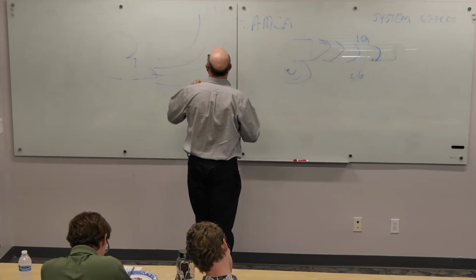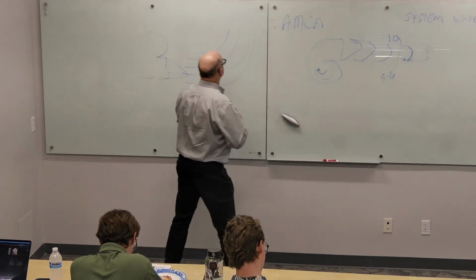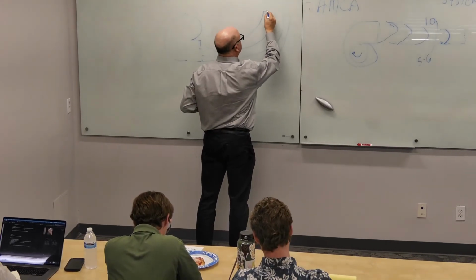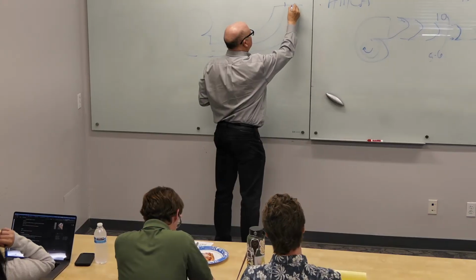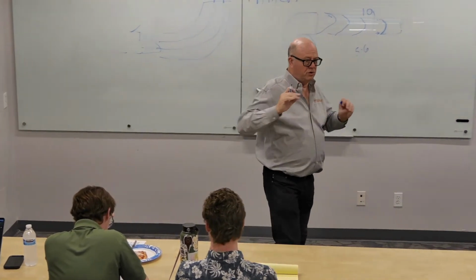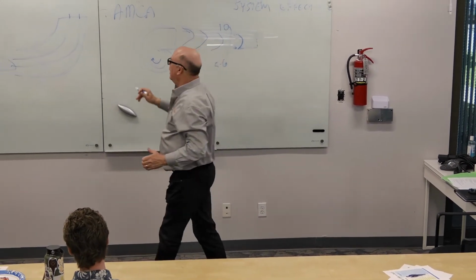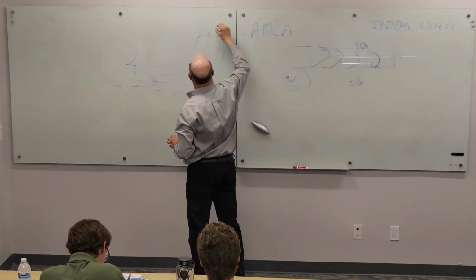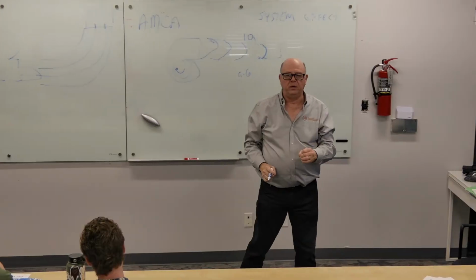Additionally, and I don't know how religious our sheet metal guys are at this, I can't say because I honestly don't know, if this is our elbow, these actually should extend slightly beyond the edge so that they slip into the next piece of ductwork. And that helps a smooth transition to that next piece of ductwork, because what you're trying to avoid is turbulence.